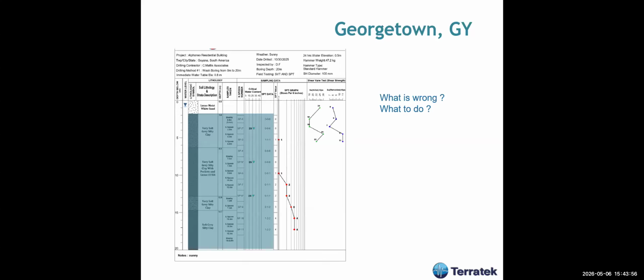We had to go at least to 30 with 3 measurements. Usually what I specify is that you can stop the borehole after you have at least 3 consecutive SPT measurements over 30. Okay.